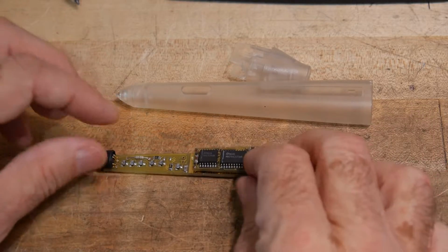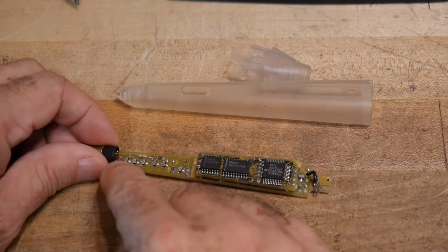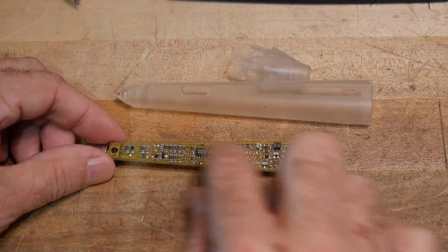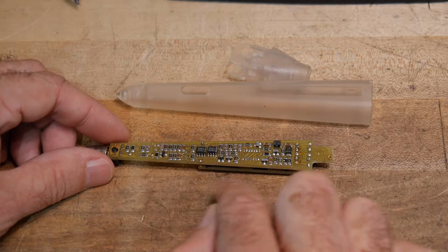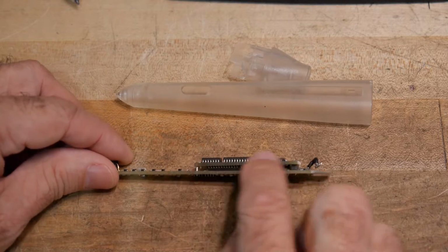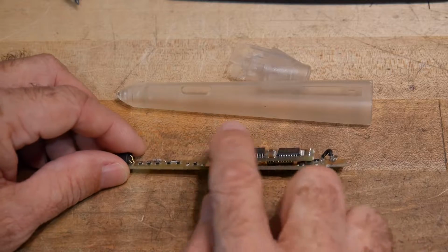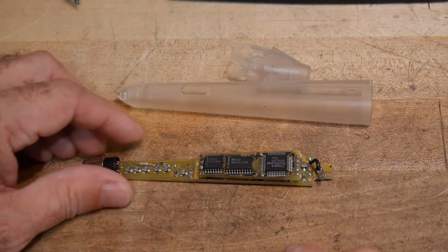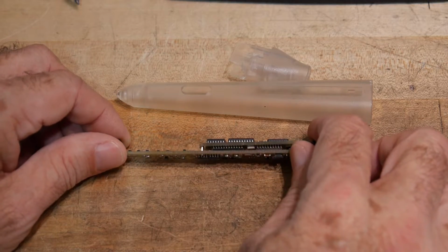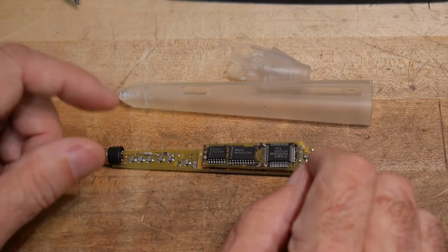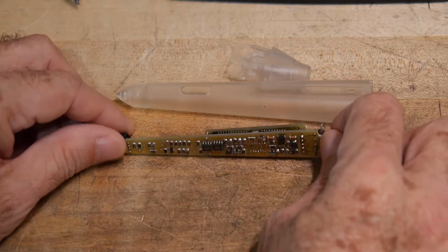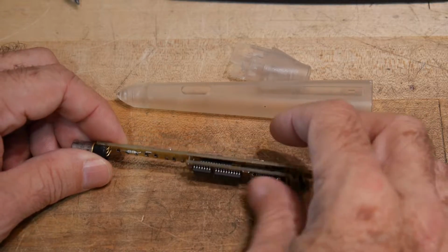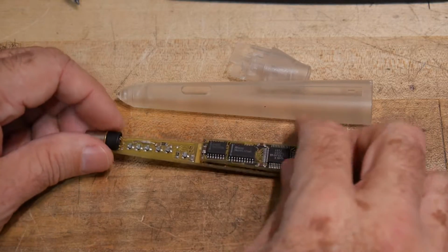This particular one, though, was what we called a smart wand, and it was able to digitize the circuitry. That's what all this is here. It digitized things into a high-low data stream, and then there was a piggyback board here that had the microprocessor on it. The microprocessor would then do that decoding, and this particular device would send it out as RS-232 data. So this was a serial interface one. The one that did the keyboard interface we'll look at a little bit later, but this one was definitely one of the first we ever built that had the actual decoding inside of it.